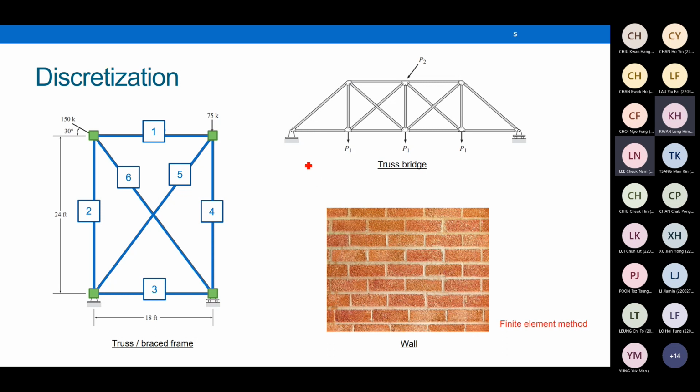One remark is that here we treat the whole member as one element. But actually, you can break this element into 2 members. You can also do it this way, if you like. You can cut one member into a set of truss members, depending on how you do the cutting. The cutting is quite general. There are many cutting methods. You do not have to keep it as one member. You can change to 2 or 3 truss members, depending on how you want to model the structure.